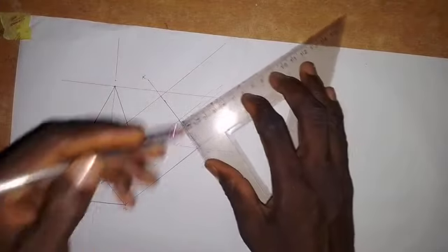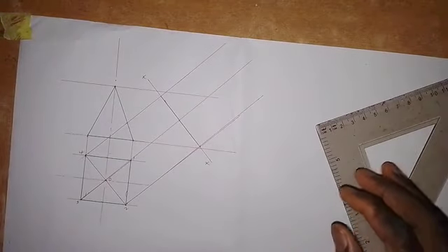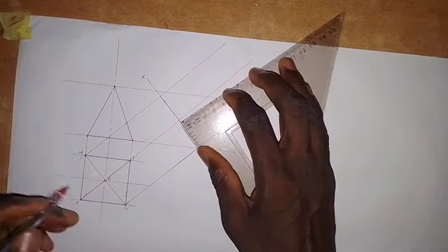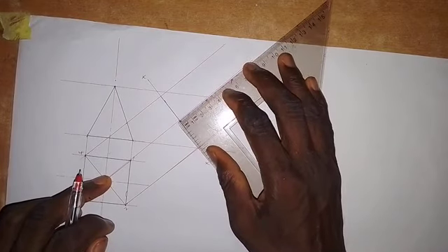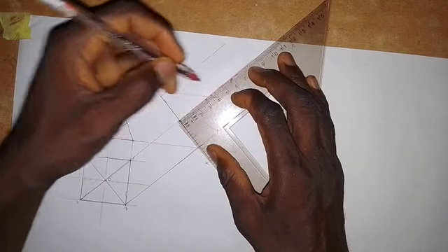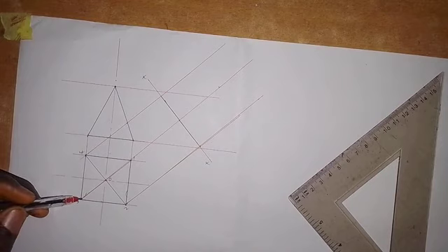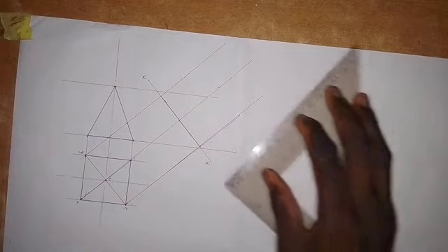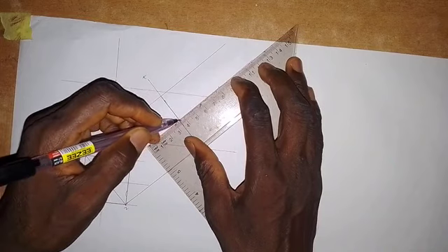The next thing that we are going to do is that as I'm looking at the object, it's a pyramid. So I need to get this point, which is 45 from the base. So I'm going to take a measurement of 45 millimeters. This is the center line. This is the center. So I will take 45 millimeters from here. So this is 45 millimeters. We are going to see a line from this point 3 that will be joined with the apex. So we have to make this line a thick line like this. Make this line a thick line.